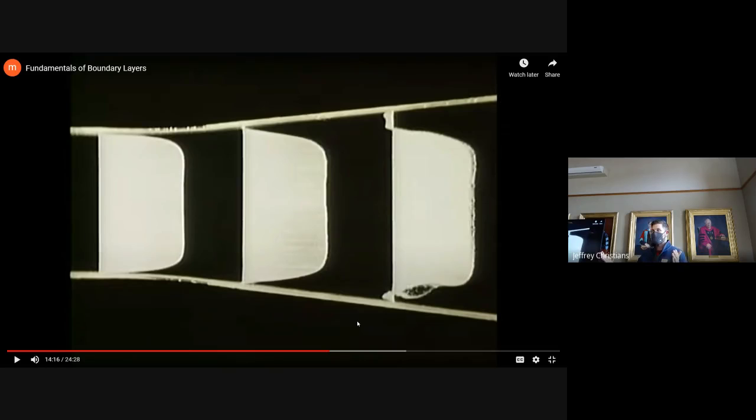So pressure is pushing from right to left, pushing against the flow. It's a force causing velocity changes. If you're a fluid particle just happily moving along in the center, you just slow down a little bit, and you move along on your merry way a little slower than before. If you're a fluid particle near the wall, you were moving really slowly to begin with, hardly moving at all. You didn't have a whole lot of inertia, and now pressure is pushing on you. It can push so hard that you come to a stop and turn around and go back the other direction.